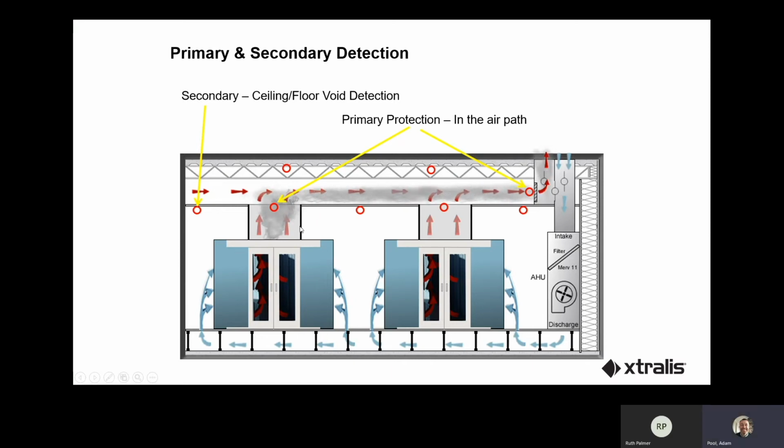But I mentioned earlier, actually, containment aisles are beneficial to fire detection because we can then start to address more directly where that smoke's coming from. If we were to detect only here, we'd only know that it's within the equipment being fed from these two containment aisles. Whereas if we also detect at the top of the extraction hood of the containment aisle, we can then pinpoint to say it's in this location here. And that's perhaps particularly important for not only trying to identify where the fire's starting, but also for the risk associated with people working in this facility. It's very important, particularly with containment aisles, that there's adequate fire detection within the containment aisle and also adequate alarm signaling in the containment aisle, so that if somebody's either working in there or is about to enter that containment aisle, they know that there's a potential problem within that space.